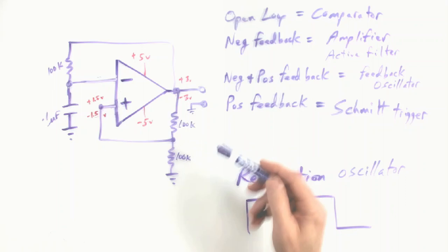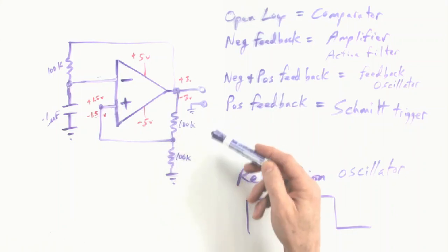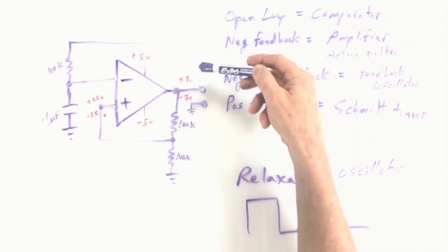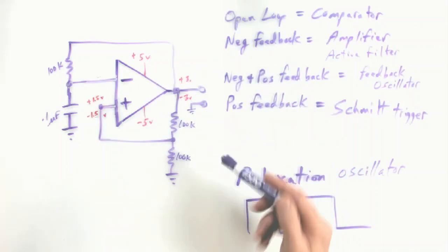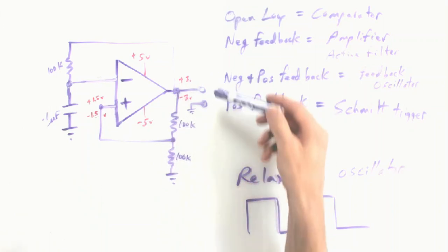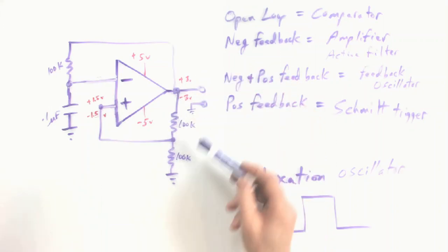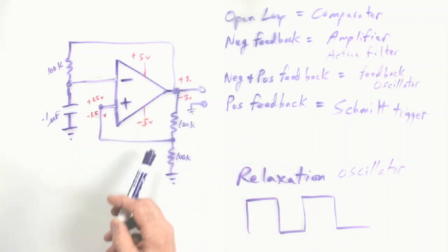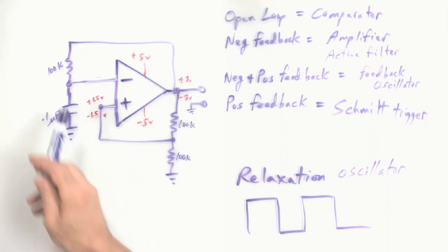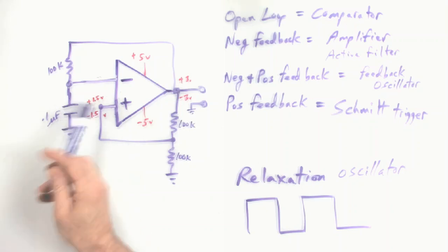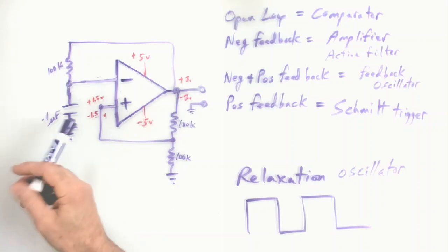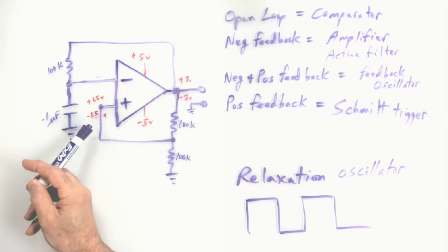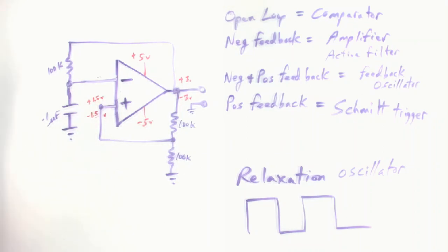Or this is optional, but if you want to try with our plus or minus 5 volts, you might expect somewhere around 3 volts at the output, a little more probably. Just to give you the idea, if the output's plus or minus 3 volts and you use 200 Ks or something like that, you could keep it simple, split it, send half of it back to the plus input. That would be our positive feedback. It's really the reference voltage because it's a comparator, and you would have the cap charge up to 1.5 and down to negative 1.5.